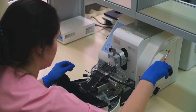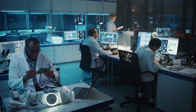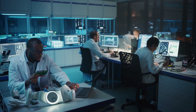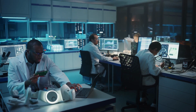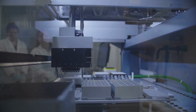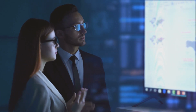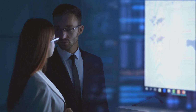Why not just change one variable at a time? Because real-world processes are complex, and factors don't work in isolation. With DOE, you can do the following. Speed up experiments. You get answers faster with fewer trials. See interactions. DOE uncovers cases where two variables combined behave differently than when acting alone.